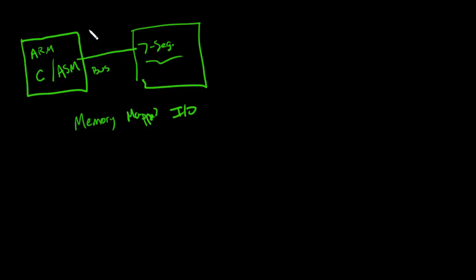And by doing loads and stores, we can essentially store values onto the memory bus, and then the hardware interprets that to map it into its internal registers, where we can even read the status of that hardware and back into our C program. So it really turns out to be load words and store words are the way that that happens.